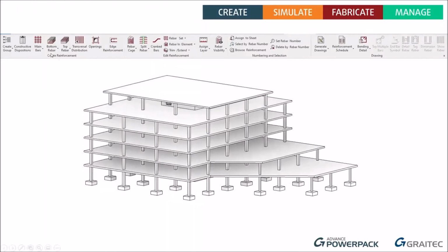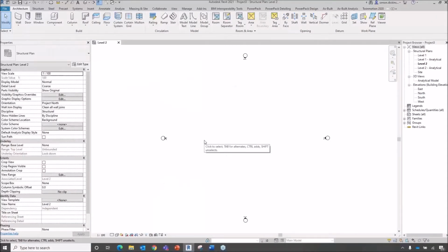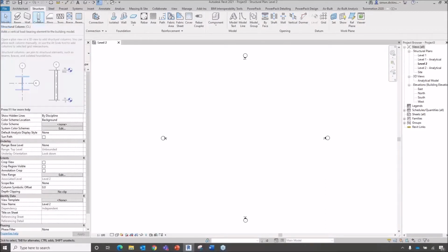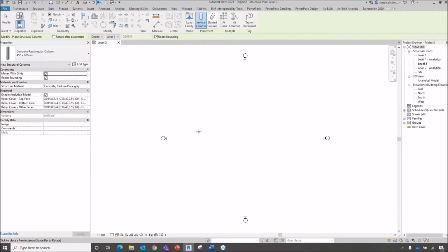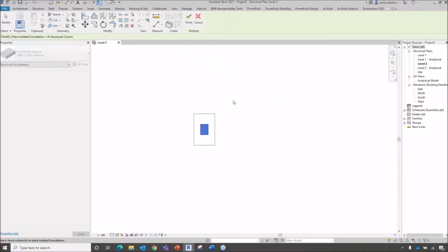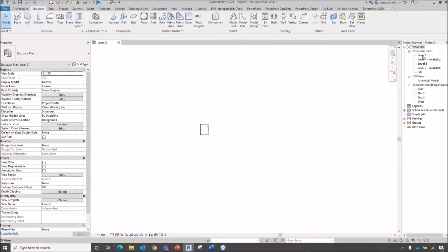So let's pop over to Revit. Okay, so here we are in Revit, completely blank model. Let's create something simple, and let's put some reinforcement in using the Revit tools. Help if we use a concrete column. Okay, so let's have a concrete column in there. Let's have an isolated foundation in there. Placed out columns. Okay, absolutely fine. Just moved it down to the bottom, which is what I wanted it to do. So here's my column and my footing.